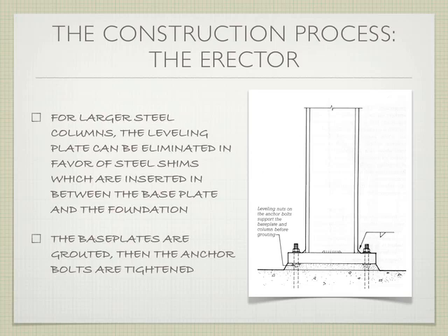This is the concrete footing here. This is the grout, because this nut or this steel shim that's inserted has to be flexible until you get the whole building plumb. Yeah, no, it's okay. It's much bigger scale. So this grout just covers up that. Just like with the prefabricated concrete, it's always grouted. The joints are always grouted. Same thing happens here.